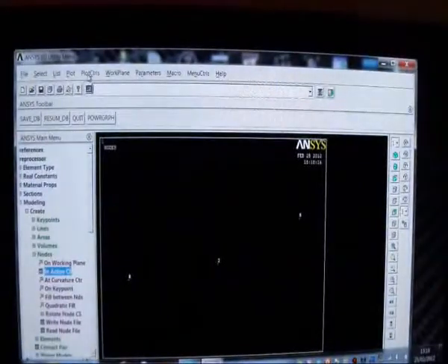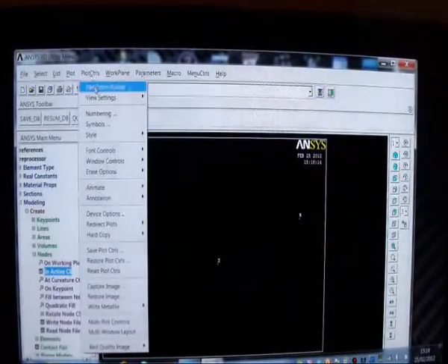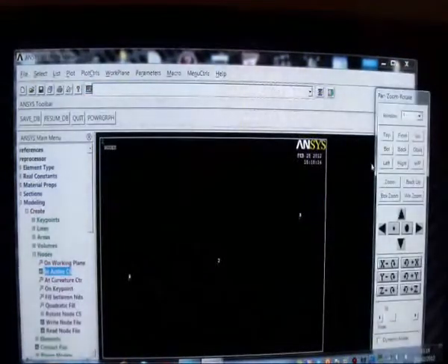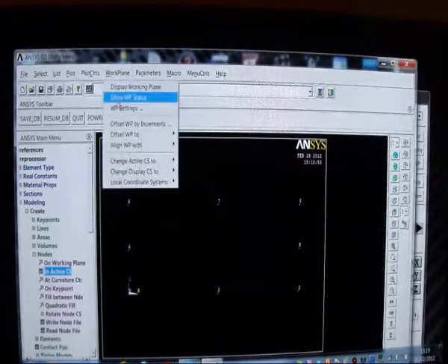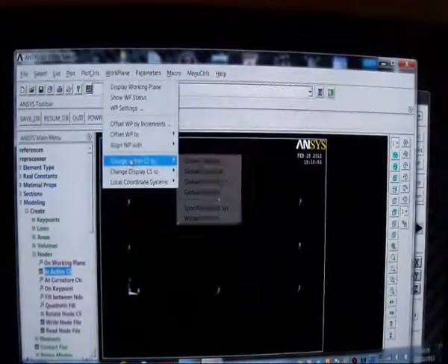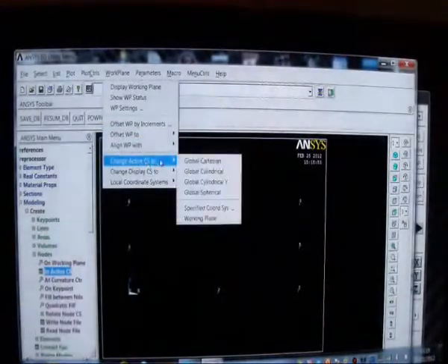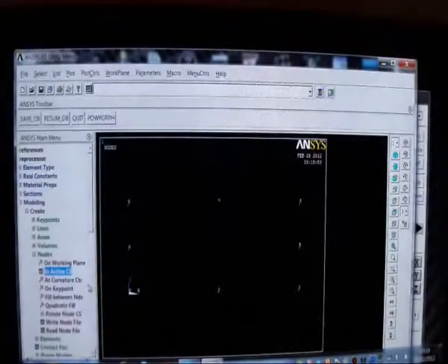I don't like that view, so I click on pan, zoom, rotate, and I'll pick on bottom there, and there I've got it. You can see the X direction. This is the X direction. It's the local direction, which is the same direction for EX. EY is in that direction, and EZ is the perpendicular plane. So I'm not going to come out of this work plane, and I must change it to global Cartesian. So I do that, and I have to create the element.